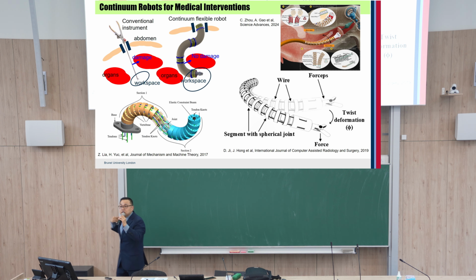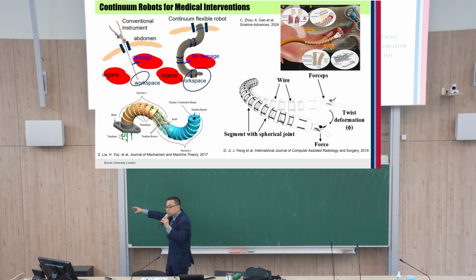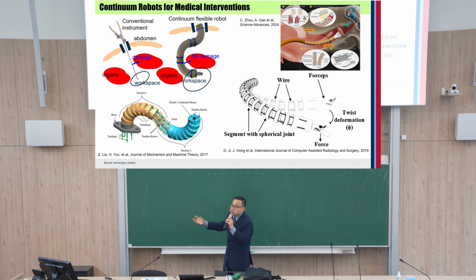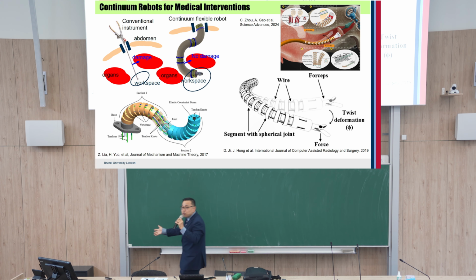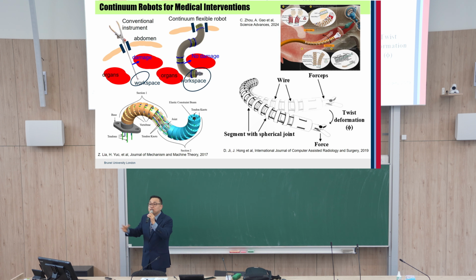Yes. Then each joint has an encoder. For that reason, once we know the encoder information, we can reconstruct the robot geometry. This is very simple, right? Here we assume the robot link is rigid. If the robot link is not rigid, using encoder information, we cannot reconstruct the robot geometry, impossible.